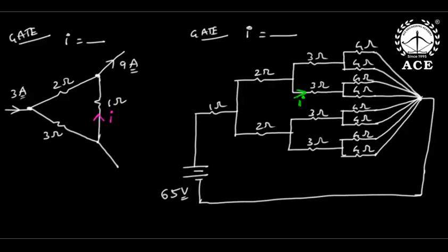Now, first of all, if you apply KCL at this entire network also, I told you our basics, KCL is applicable at a node, everywhere. If you apply KCL in the entire network, incoming currents equal outgoing currents. This is 9, so total incoming also should be 9. This is 3 already, then how much should this be? 6. So 6 plus 3, only 9 will go here.